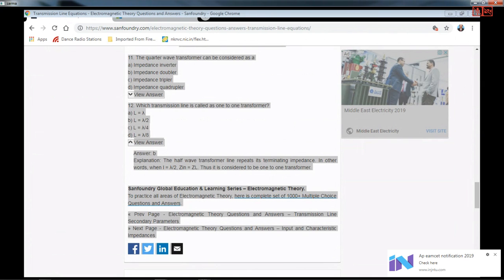This is the way the voltage wave is represented in terms of capital gamma. Similarly, the current expression can also be worked out, and it comes out as IL by 2 Z naught, e power gamma Z prime times (1 minus capital gamma e power minus 2 gamma Z prime).